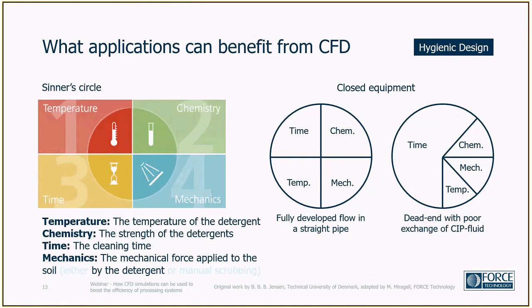And since there is a poor exchange of cleaning in place fluid, the action of both mechanics, chemistry, and temperature is reduced, and the time here takes the largest portion of the cake. And this means that we will need more time to get a cleaning efficiency similar to the one in this case here.